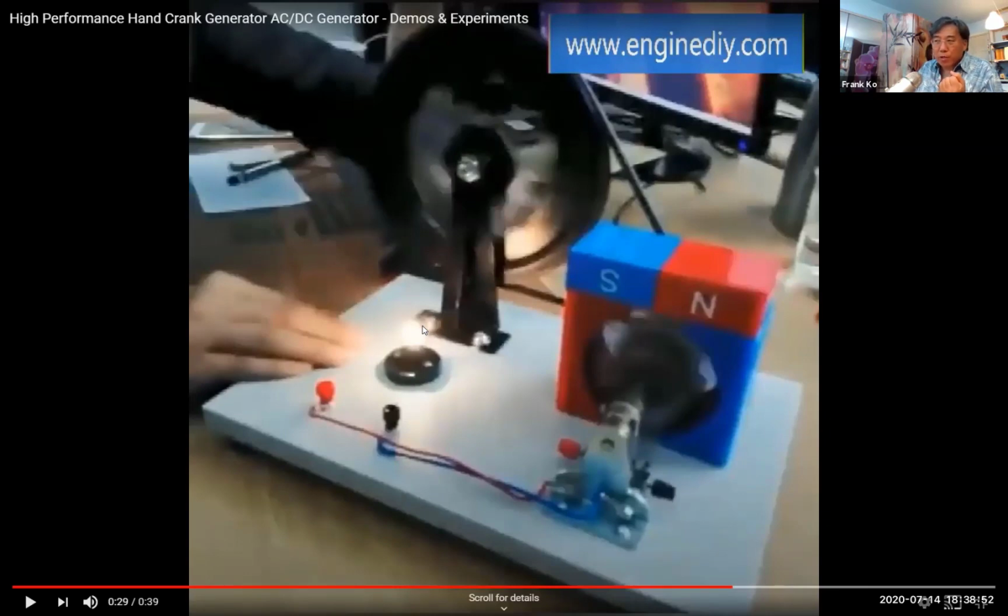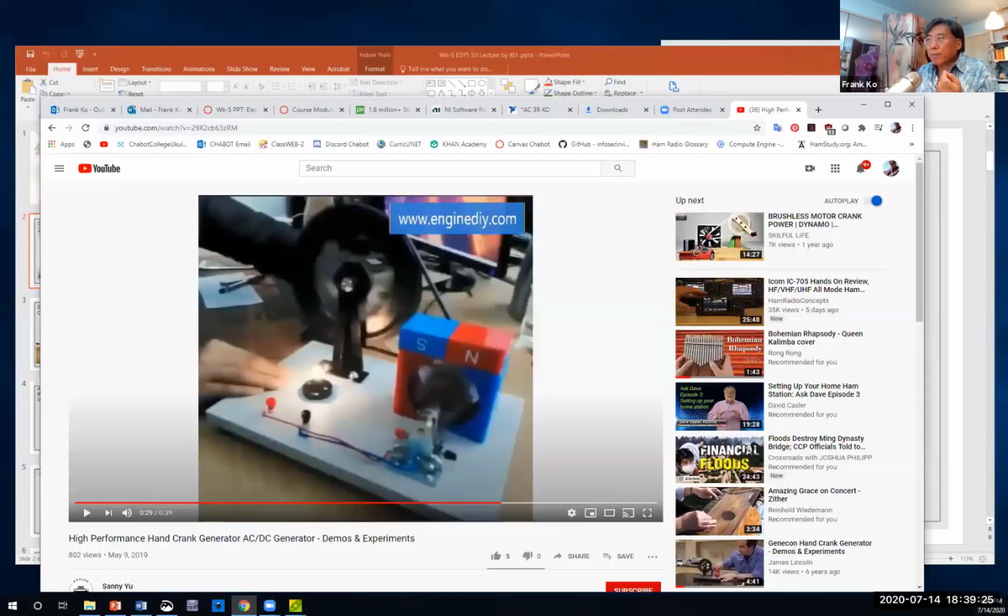And all that we're doing with a DC generator is changing mechanical energy into electrical energy. So the mechanical energy of the big flywheel with the handle is attached via a belt to a spindle that has a rotor on it. And as this rotor with wires spins around in the magnetic field, electrical current is going to be generated in the wire that will be carried through to these binding posts. Now, the next, and we can go ahead and dispense with this guy for just a moment.